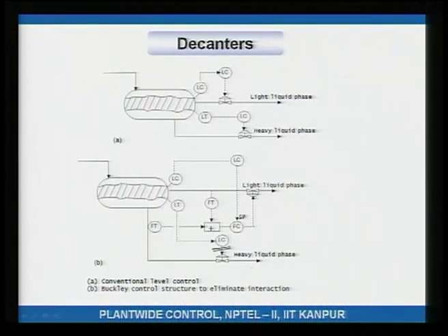Because the flow out increased, this level will start to decrease, will go down. Now, what will this guy do? This flow has gone down because you are taking out more heavy liquid. So, because this flow has gone down, this flow is where it was. So, this has not changed. Therefore, this signal goes down, set point is where it is. So, what does this flow controller do? It will start to maintain. So, total flow has gone down, therefore, it will what? Open.